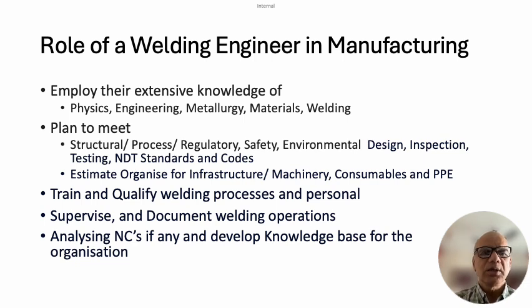The second is to meet the structural requirements. If it is a bridge, you need to consider the structural rigidity of these parts. Accordingly, the joints, the trusses, the overlap, the joining of materials are decided. The process can be a carbon steel with stainless steel overlay to get corrosion resistance. It can be alloy steel with suitable heat treatment to achieve higher hardness or strength.